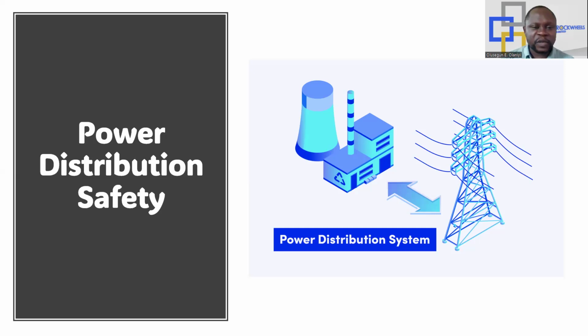Here, you will agree with me that we have different components, just as we have discussed in other sections on generation and transmission. In distribution, we have the transformers, the switch gears, the circuit breaker, the bus bar, and the conductors. There are many. The transformer steps down voltage from the levels of transmission to distribution level. The switch gears control and protect the electrical equipment in the substation. The circuit breaker provides overcurrent protection and can disconnect circuits during fault.